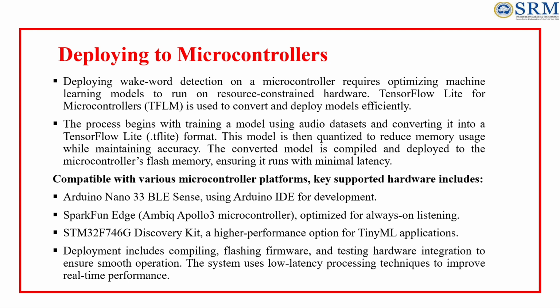Here's the process. First one, training the model. We start by training our wake-word model on a dataset of audio recordings, for example spoken words like yes or no. Second, converting to TensorFlow Lite. Once it's trained, we export the model into a TF Lite file.